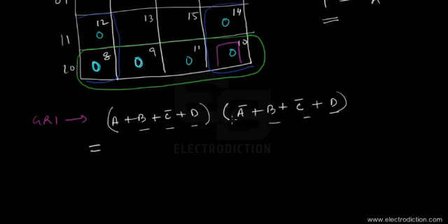So you just extract them out, and whatever remains over here, you can see that A and A bar are both complementary quantities. I'm just jumping the steps over here, but if you would care to take all the pain to multiply these two quantities and solve them using De Morgan's theorems, you'll find that the ultimate solution would result in B, C bar, and D. It's quite a tricky way to shorten all your effort if you just take a look at the common terms, and the rest will all be available in complementary values.